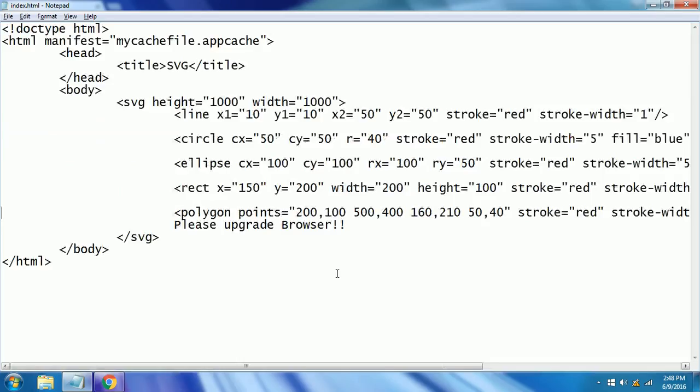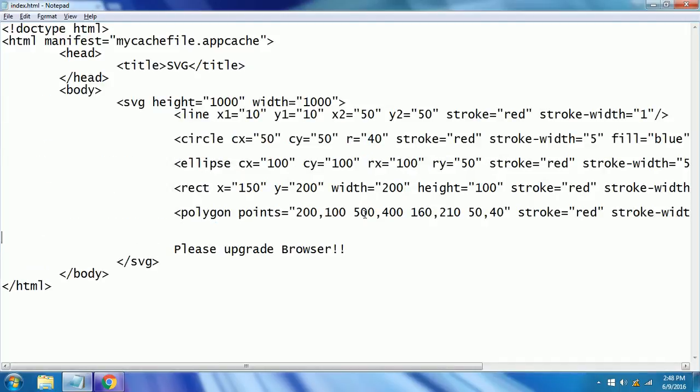And yep, the next one is polyline. I'll start from here so that we can see everything. How to draw a polyline? Again, the same as before, you have to define the points. So I'm saying some 900 comma 1000 coordinate.